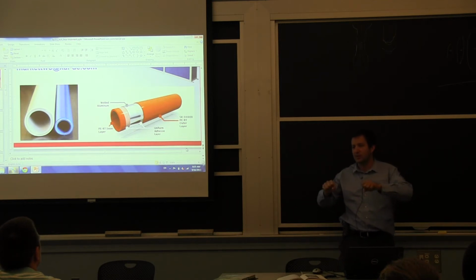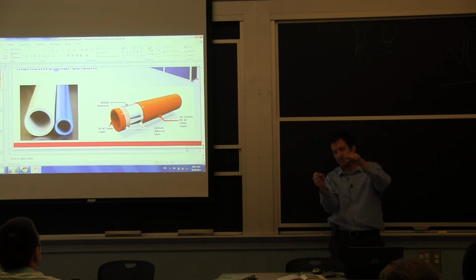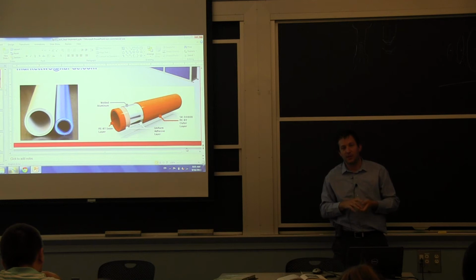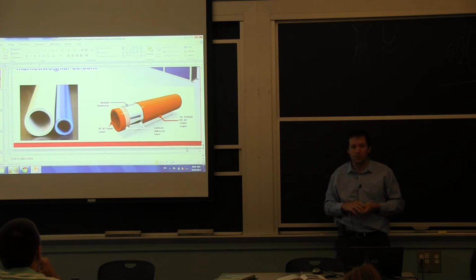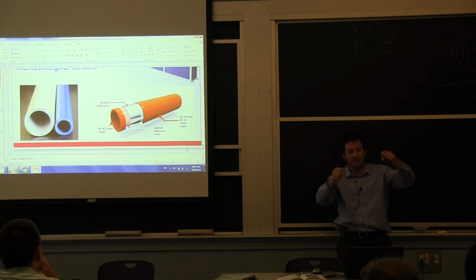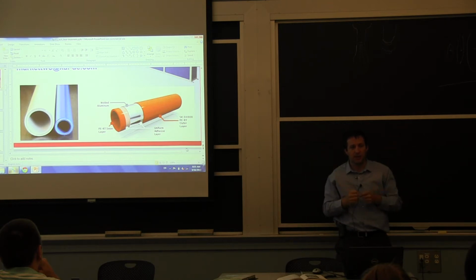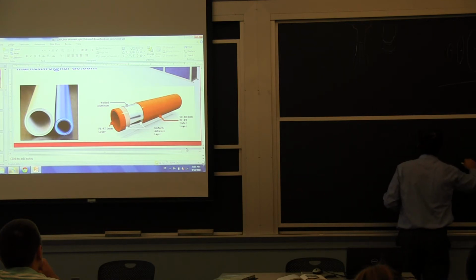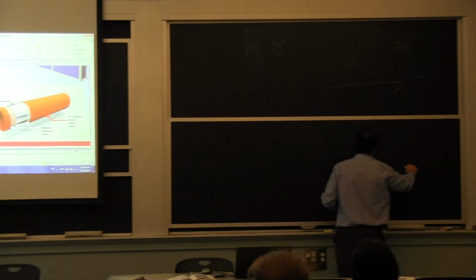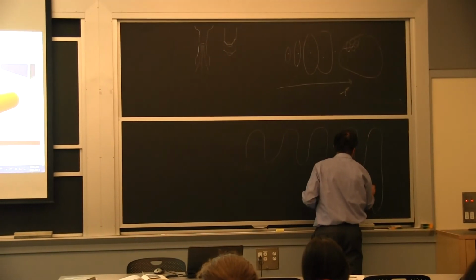I should have brought some pieces, but the advantage of this tubing is you can bend it and it will keep the shape because the aluminum deforms plastically and it will build in the new geometry. It's formable. The regular PEX, you bend it, but it's elastic, so it's going to come back on you every single time. If you're in the slab, you're going to want to do this shape so you have more coverage, and then you tie it back to another loop,